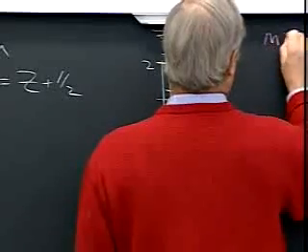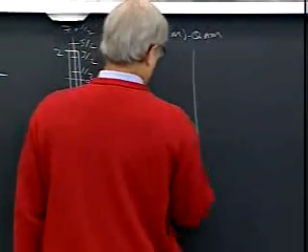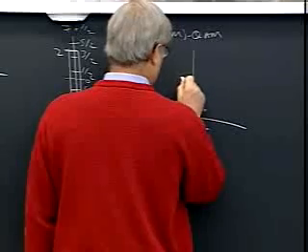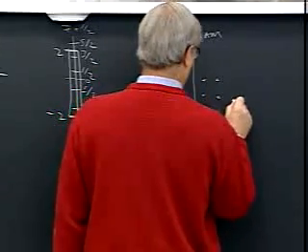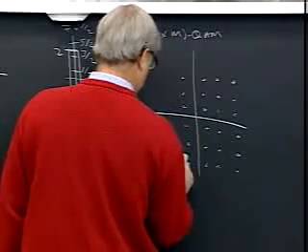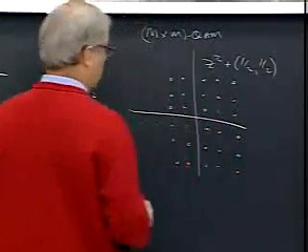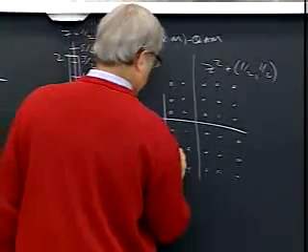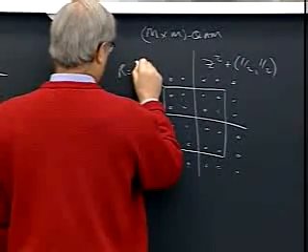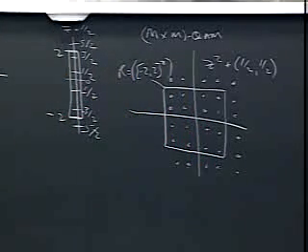Similarly for M by M QAM, like everything else, it's just doing the same thing independently in 2 dimensions. Here we take our lattice to be Z plus 1/2 squared, which is just Z squared offset so as to be symmetrical to 4-way, 90-degree rotations. So here is Z squared plus 1/2, 1/2. Then again, to get 16-QAM, for instance, we might take the region to be [-2, 2] squared, which again has area 16.